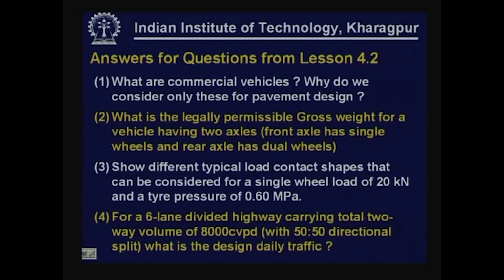Of course, we have to adjust this for using appropriate vehicle damage factor and then convert this into equivalent standard axle load repetitions. That in fact is the input that we are going to use for pavement design.